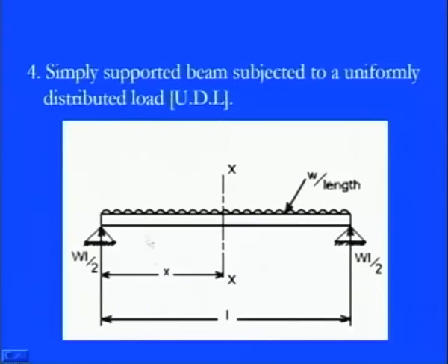If these two extreme corners, point load is this concentrated load, which can be easily obtained if you know the distance, this L, and W is there. So the total W into L is the load applied, and due to that the shear force as well as the bending moment will come. The reactions, due to the symmetry, will always be equal to WL by 2 at this point and WL by 2 at this point, both acting in the upward direction.